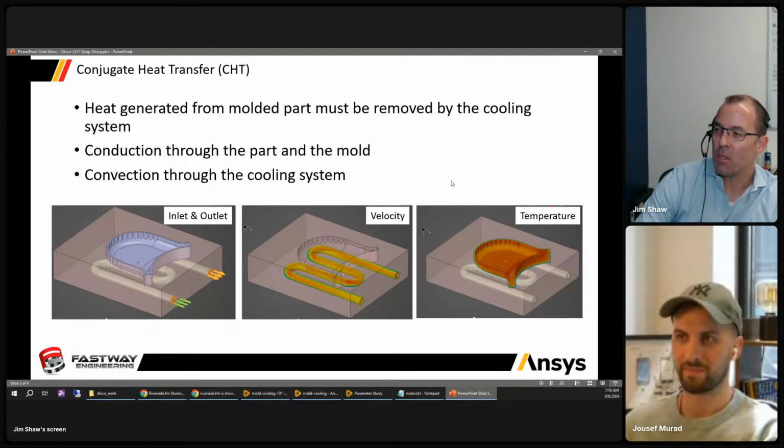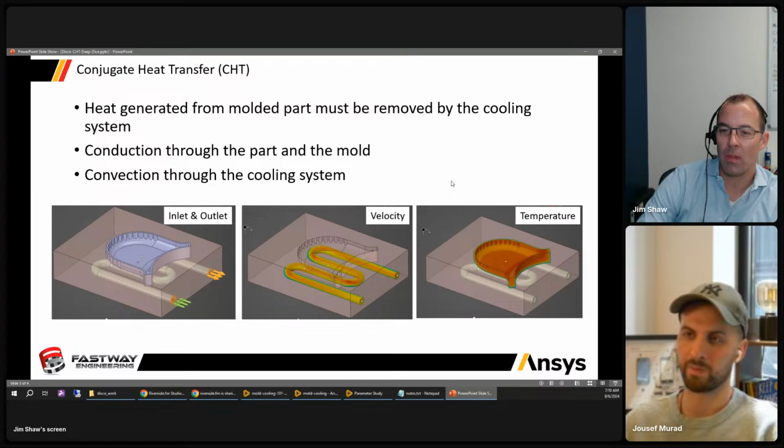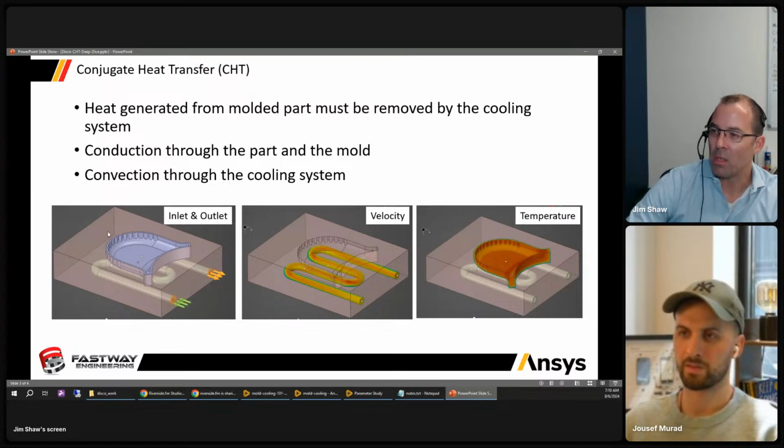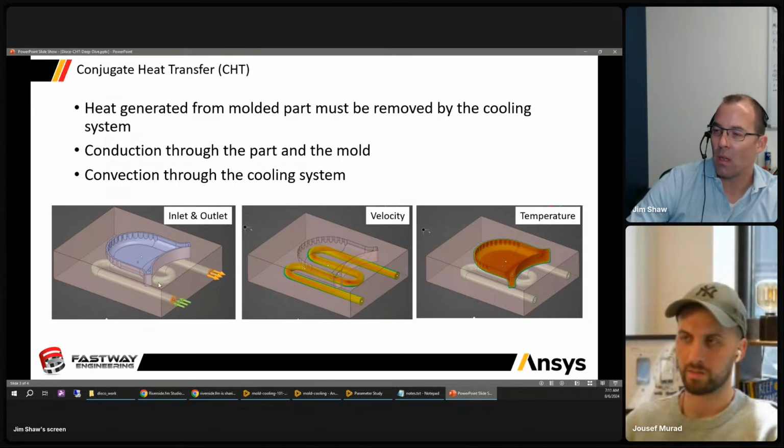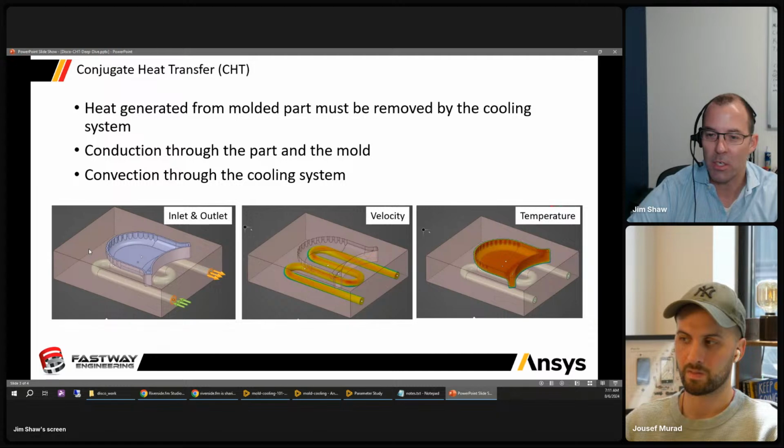And all we're trying to do is understand a couple things, right? One, we want to understand the heat transfer. So I've got a thermal load that's being generated by this part. Now, in real life, in the molding process, what happens is I bring in a molten polymer, right? And then it's solidified. So the initial temperature on this mold is going to be whatever the melting temperature is of that. We're not getting into that level of physics, right?